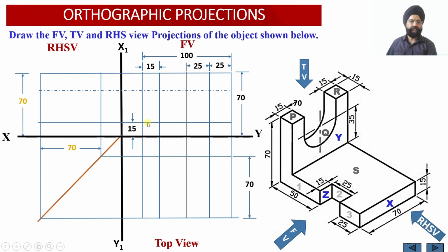So we had drawn the top surface of the horizontal web over here. Now we are going to mark 35 millimeter above this top surface of the horizontal web, that is 35 millimeter above the surface S over here. This distance we have marked so that we can obtain the center of this particular circular portion in the front view. Once we mark this center, we automatically get this vertical portion of this slot on the vertical wall. So this vertical section will be equal to 20 millimeter.